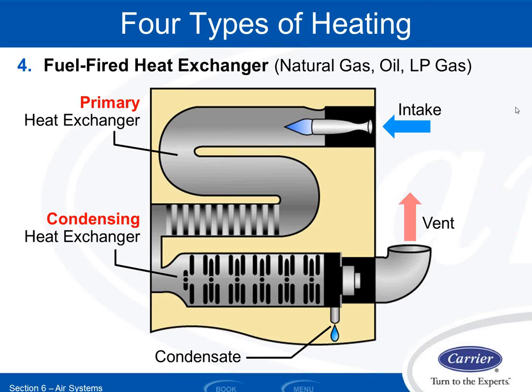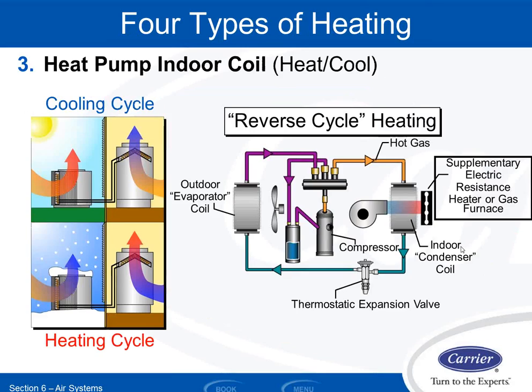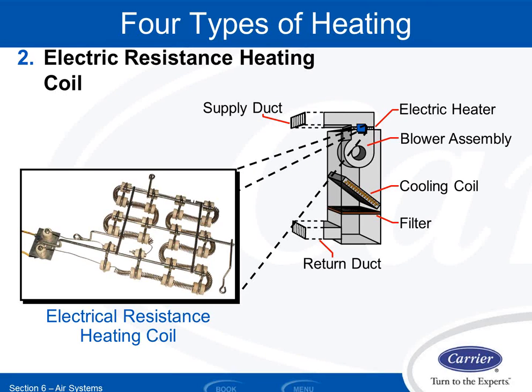Now, my other heating sources, right, for example, I'll go back a little bit here, my electric resistance heating, that's basically 100% efficient, right? Every kilowatt hour I buy from the electric utility gets converted into usable heat. Now, it could get a little bit of an orangish glow to it, so there might be some light output, if you will. So maybe you could say that it's 99.999%. But I would argue that eventually that light will land somewhere and heat that surface up. So it's basically 100% efficient for electric heat.